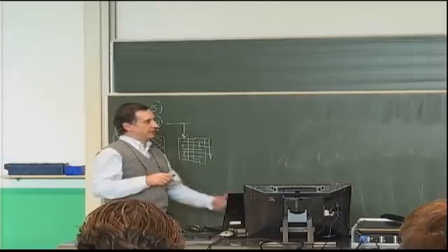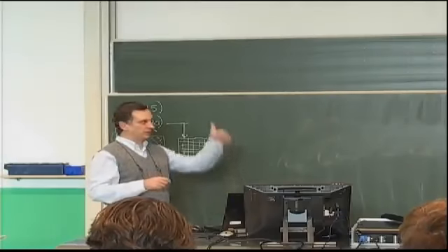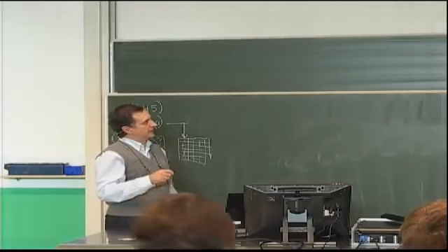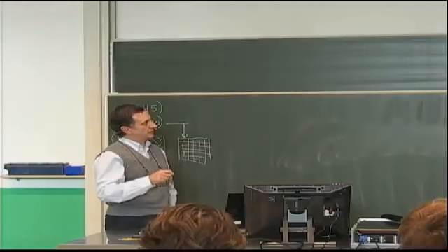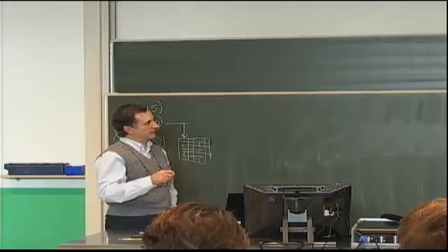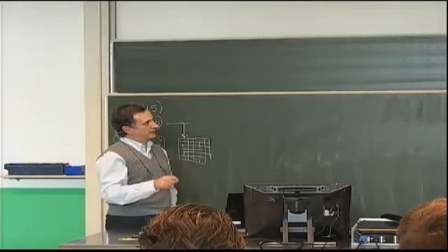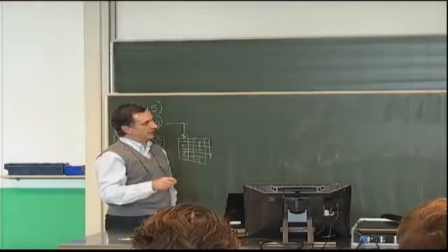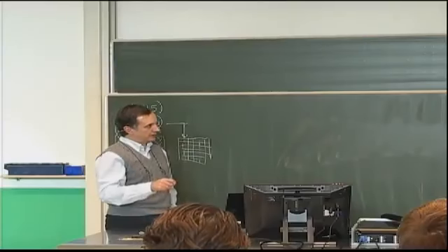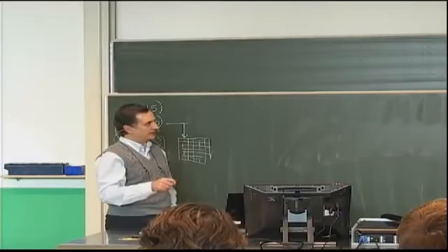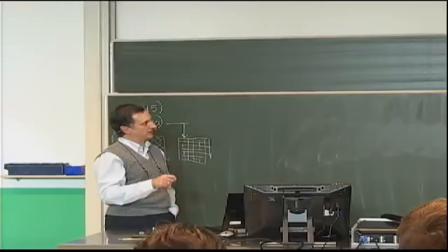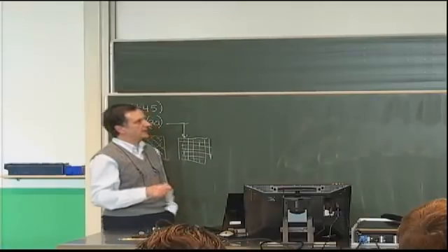Qz, minus Qz is the out-of-plane load. If I take my Qx and Qy definitions, or from the equilibrium equations, which are in terms of the moments, I can substitute in this to arrive to this equation here. Now, in the slides posted, this says 0. It's obviously a mistake. It should say minus Qz. It's the right-hand side of this equation here.